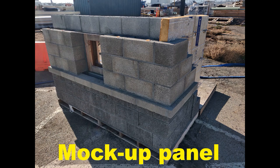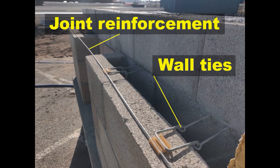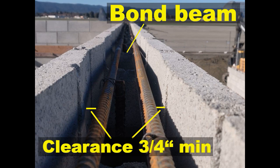Mock-up panel location. Show full color range, texture, and bond pattern of the masonry work. Demonstrate mortar joint tooling, grouting of reinforced vertical cores, collar joints, bond beams, and lintels, positioning, securing, and lapping of reinforcing steel, positioning and lapping of joint reinforcement, including prefabricated corners, and cleaning of masonry work during the construction of the panels. Also include installation or application procedures for anchors, wall ties, CMU control joints, insulation, and flashing.